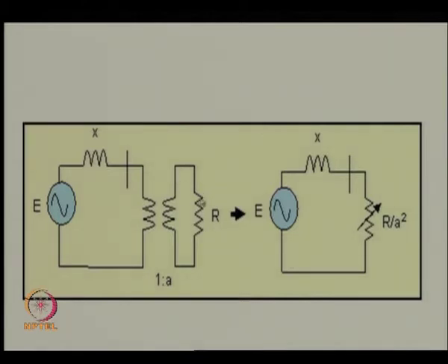You have a load resistance which actually does not change, but it is supplied from a tap changing transformer. The tap of the transformer keeps changing. So, if the voltage here drops, the tap A is increased. If the tap A is increased, the effective resistance which the system sees is in fact variable. So, although I talked about a variable resistance, a more typical situation is likely to be like this. Of course, the same issues are here too. In fact, the same arguments are valid here, because this tap A is increased whenever the voltage here falls.